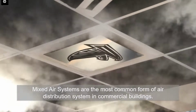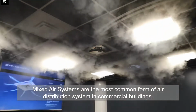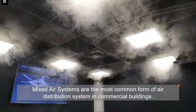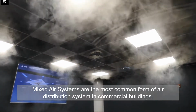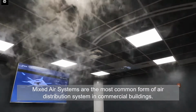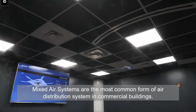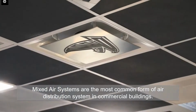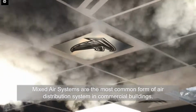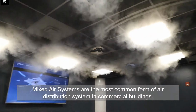The videos we'll show here are from our flow visualization room in Atlanta. This is just theatrical smoke. It's kind of like a fog machine you'd see at a concert, but we put it in the ductwork and use that to visualize how the air moves throughout the space. What we're seeing here is a standard square plaque diffuser, used in what we call a mixed air system. So the air is being discharged at the ceiling, typically at a high velocity at whatever design CFM we need, moves across the ceiling, and then fills out the rest of the room.